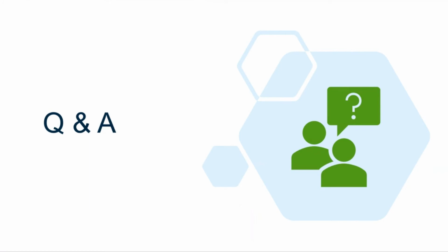The dref, is that the same thing as an xref? Yeah, good question. It is not. An xref is a whole file. You're going to xref in another DWG file. A data reference is pulling in just that data shortcut that was established. So we might have one file where we've got 3 or 4 different alignments all drawn out, and each of them is a separate data shortcut. And the dref is the thing that says, I want alignment 2 to land in this drawing. So that is different. And the other thing that comes with it is because it's not just the 3-dimensional graphics, but it's data rich, you can start labeling and have some intelligence too. So the reference inside of the consumer drawing is data rich then. Okay, I hope that answered that question.